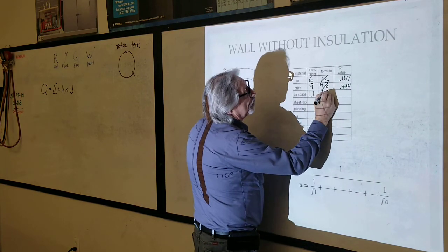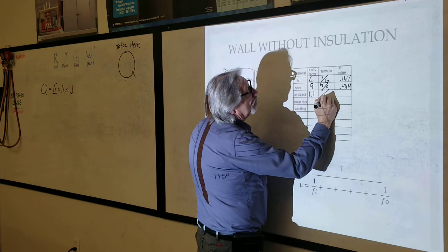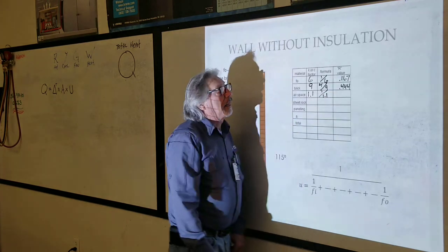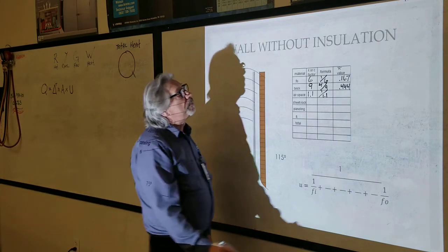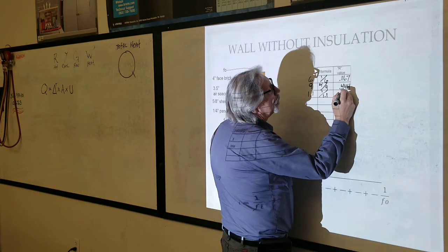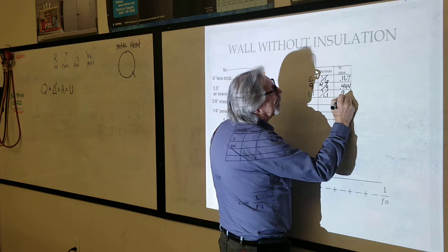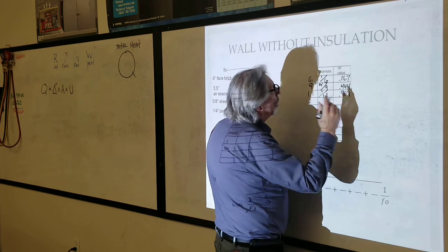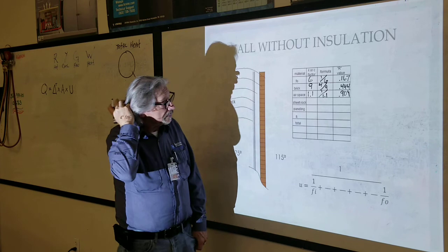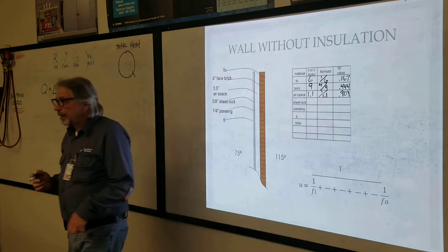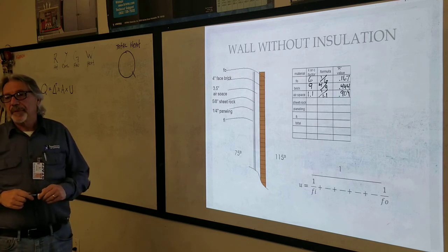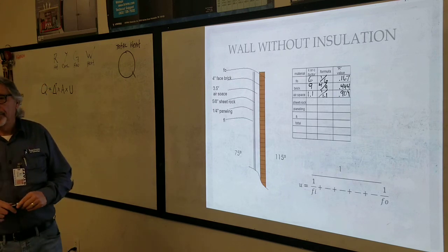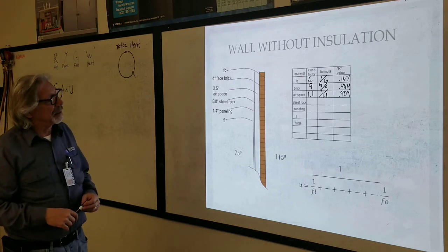So our airspace C factor is 1.1. So we're gonna reciprocate that to 1 over 1.1. And that's gonna give us the resistance. 0.909. Okay. So would you get the 1.1 again? That's just because it's in that paragraph where it talks about the airspace in walls.